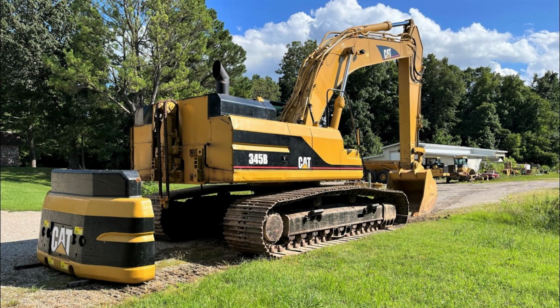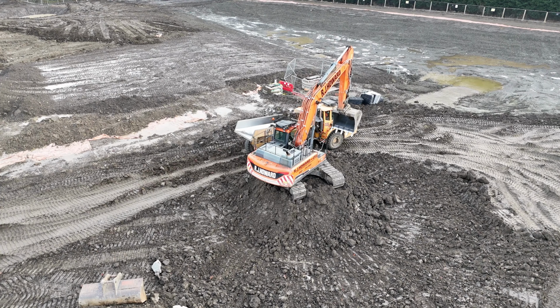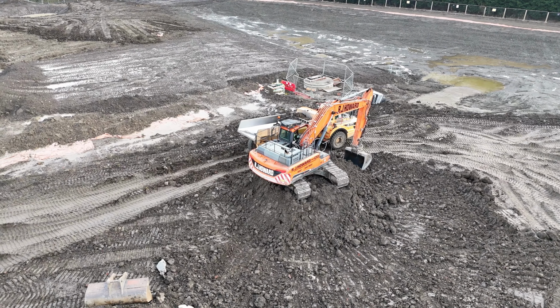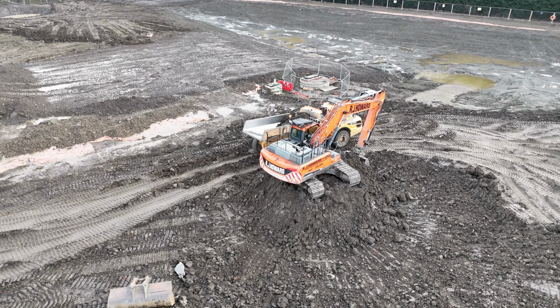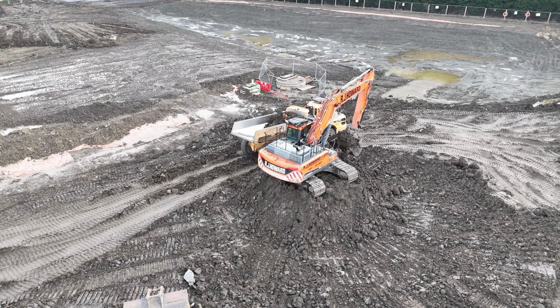To ensure stability, excavators are equipped with large counterweights mounted at the rear of the upper structure. These counterweights are carefully sized and positioned during the design phase to shift the machine's center of gravity toward the rear, thereby increasing the resisting moment against forward tipping when the boom and bucket are extended. The counterweight effectively balances the mass of the boom, arm, bucket, and payload during digging and lifting operations.